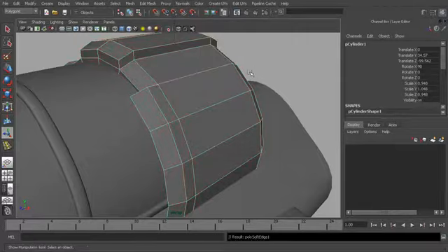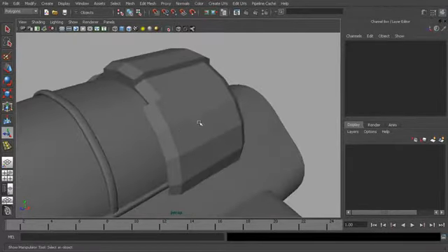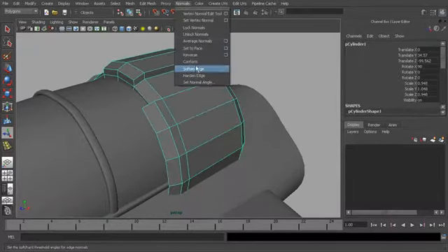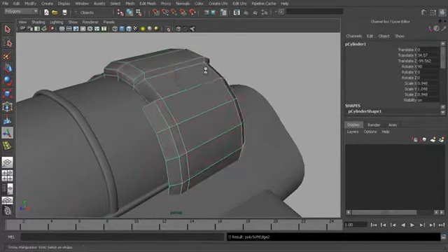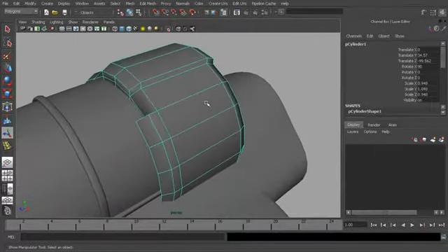And if we harden all the normals, you can see that it's very faceted. So every face, you can see where every face is. Okay. If we smooth everything, soften edge, everything is smooth. So everything is smooth between. There's really no definition. So what we want to do is set a particular angle. So any edge or any two faces that are within a certain parameter or angle value will get smooth, and anything above that will be hard.